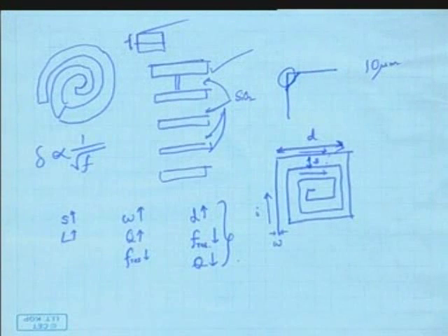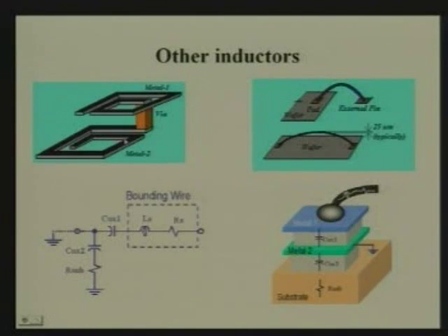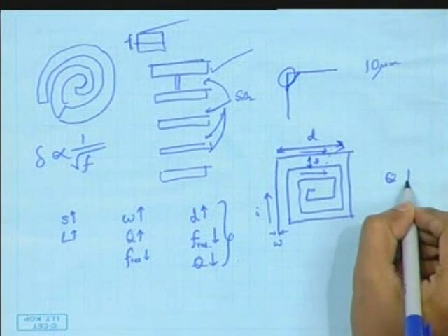Okay. Now suppose we have a huge number of turns. So people fabricate the inductor in two layers. So we get a few turns here and another set of turns here. Now the problem with this structure, can you guess the problem? Resistance losses. Yes, resistive loss, so the quality factor will degrade. Another one?